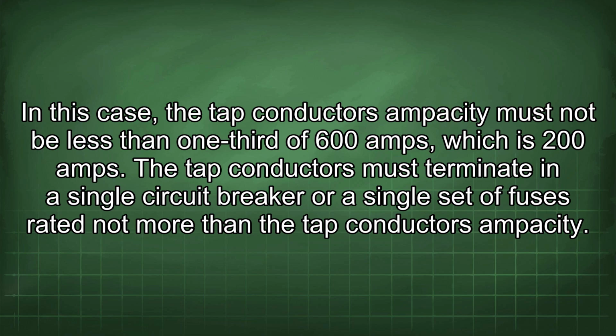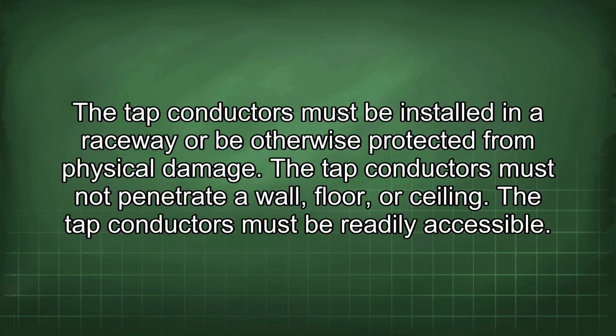The tap conductors must terminate in a single circuit breaker or a single set of fuses rated not more than the tap conductor's ampacity. The tap conductors must be installed in a raceway or be otherwise protected from physical damage. The tap conductors must not penetrate a wall, floor, or ceiling. The tap conductors must be readily accessible.